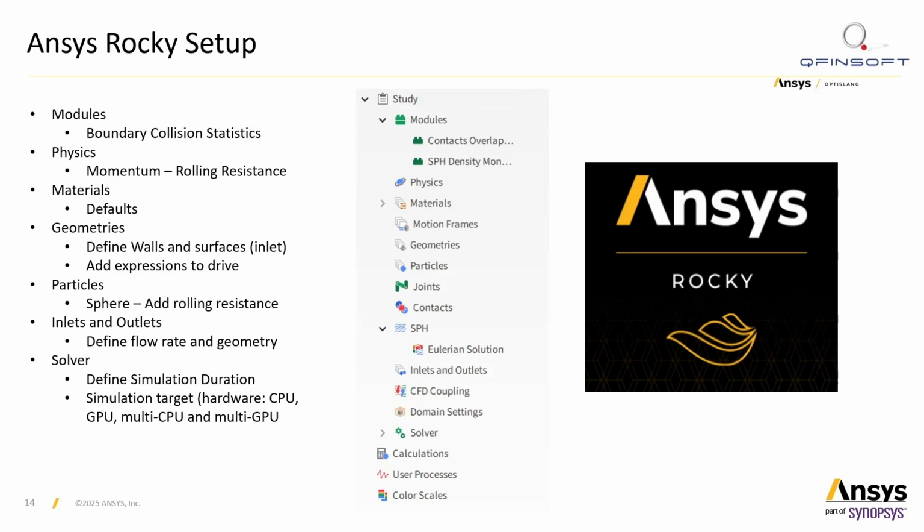We then define inlets and outlets. Inlets define the flow rate of the material entering our domain. Then on the solver side, we define the simulation duration, and then we can choose if we want to use a CPU, GPU, or multi-GPU or multi-CPU.